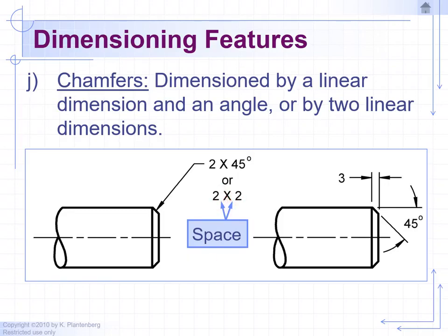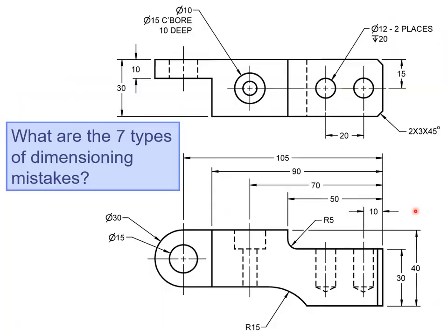Next slide. Let's practice our drafting again, how to place and call out dimensions, or how to correctly label dimensions and use symbols. Right off the bat, we should avoid using words. This was acceptable 50, 40, 60 years ago, but in the last few decades we got away from using words. Instead of counterbore, we'll use the U shape to define a counterbored hole.